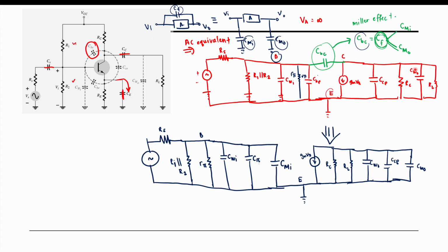We didn't change the configuration type, it's still a parallel connection. Only the position changed, because it's easier for us to calculate later the value of the impedance and the capacitance, since we put all the capacitance in one place and all the resistors in one place. I hope you understand how to draw this AC equivalent circuit.